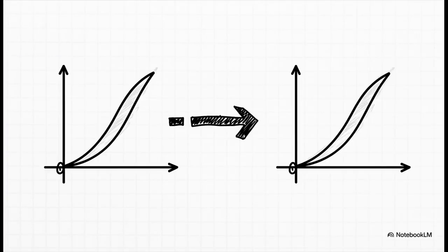Okay, first tool, the angular shift. This is all about timing. Our standard function always assumes the motion starts at a CAM angle of 0. But what if you don't want it to start there? What if your rise needs to kick in at, say, 120 degrees? No problem. You just go into the standard equation, and everywhere you see a theta, you replace it with theta minus 120. That's it. It literally just slides the whole curve over to start right where you need it.